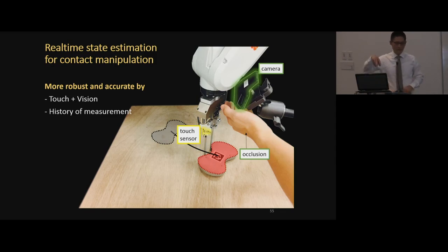Yeah, so in that collection, we didn't intend to insert that object. So we're just exploring around the whole of the object. The exploration strategy is, we have roughly 2 centimeters of translation error and 15 degrees. We try to just move down until contact, and we just enumerate in that range.